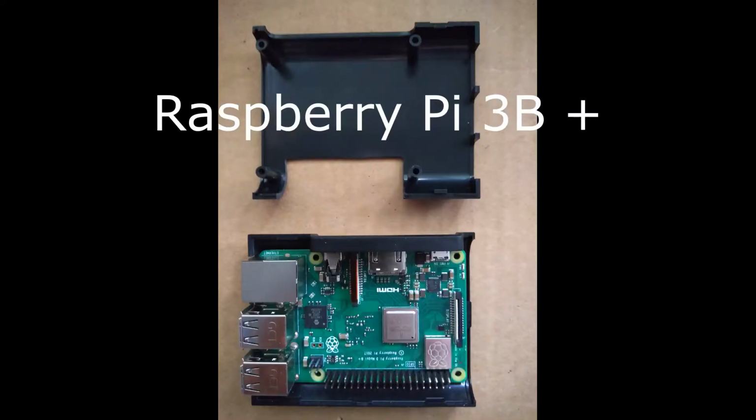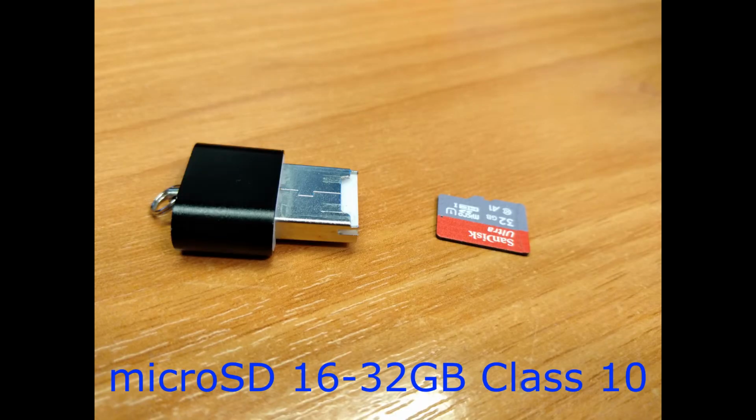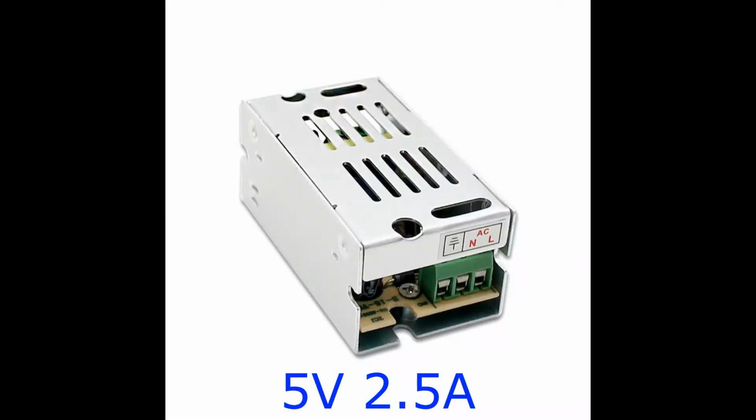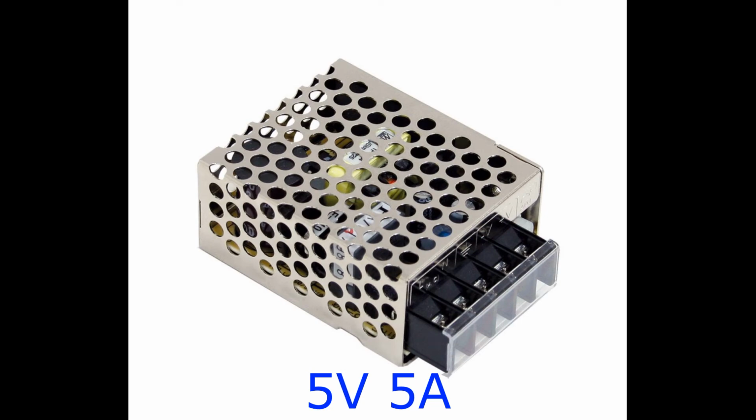This is a DIY project, it's not so hard to assemble it, but anyway, you should be aware about hardware to buy. All we need is the Raspberry Pi computer, Raspberry Pi 3B Plus and Raspberry Pi Zero tested only. A microSD card for the Raspbian operating system. Matrices 8 to 32 WS2812 LEDs. Two 5 volts power supplies. 2.5 amperes and 5 amperes for Raspberry and LED matrices respectively.